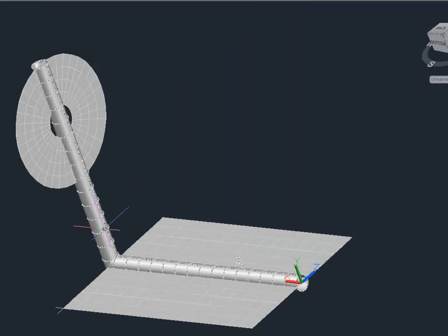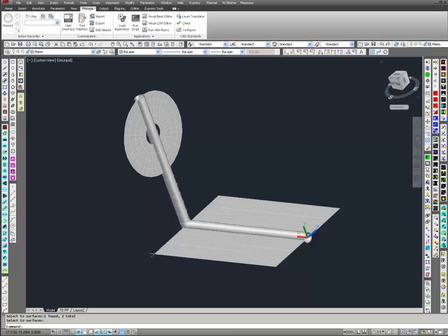I basically have a cylinder that's cutting right through the disc, it's cutting right through the plate. I'm not bothering to offset it just for demonstration purposes. And I also didn't bother to do anything about this section of pipe that's really not touching anything. So I'm going to let the contactor do the work for me and just taper off any contact anytime the pipe can't reach any object that it was assigned to. But that's enough to be able to run the model.